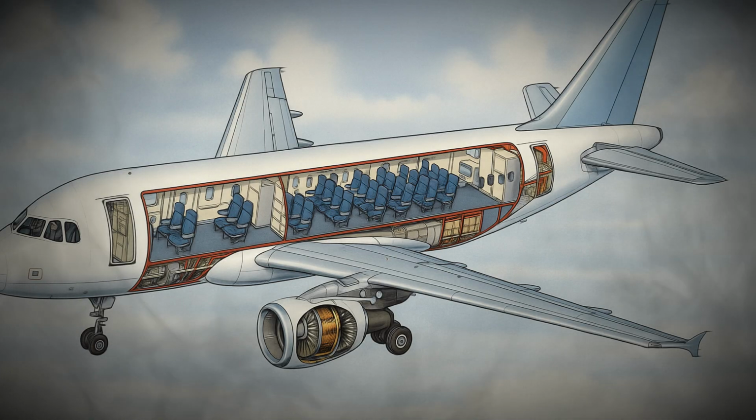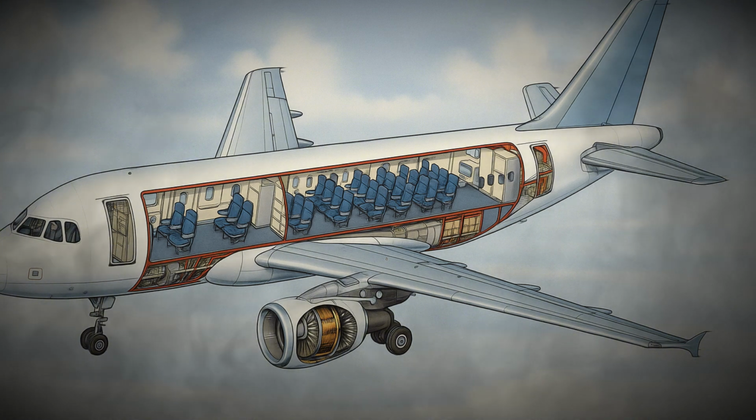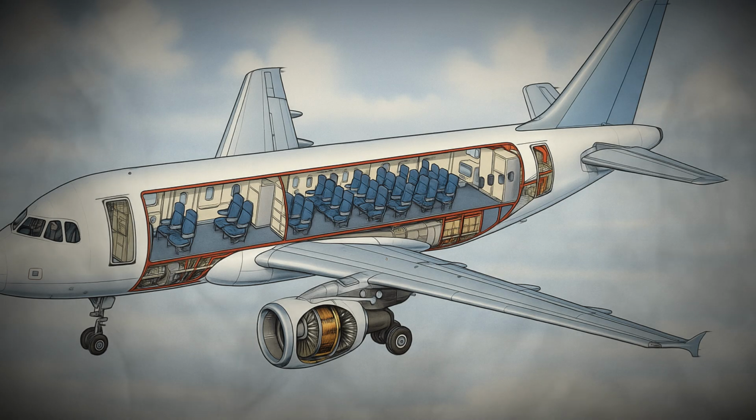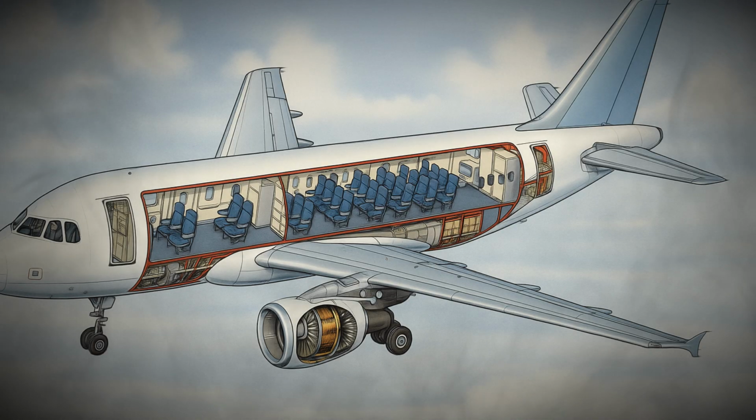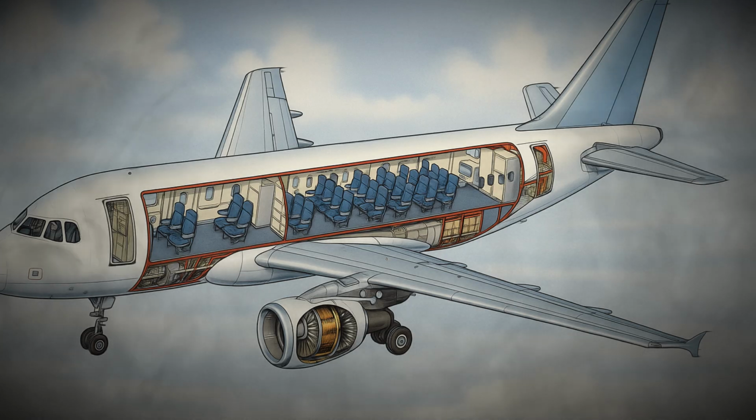Fly-by-wire systems use computers to interpret pilot inputs and apply only those commands that remain within the aircraft's structural and aerodynamic envelope. This means that if a pilot tries to pitch the airplane too steeply or roll too aggressively, the computer will moderate the command to prevent a stall or overstress. This protective function allows pilots to focus on flying without fear of pushing the airplane beyond safe performance.